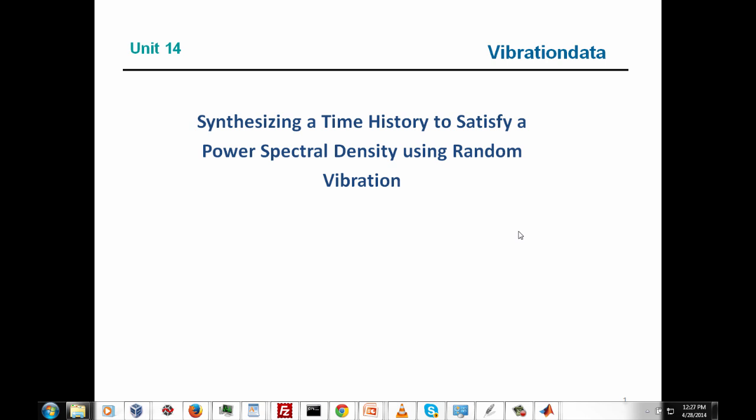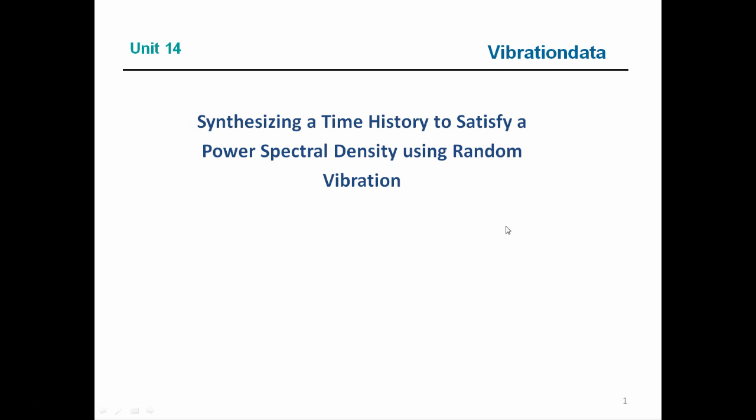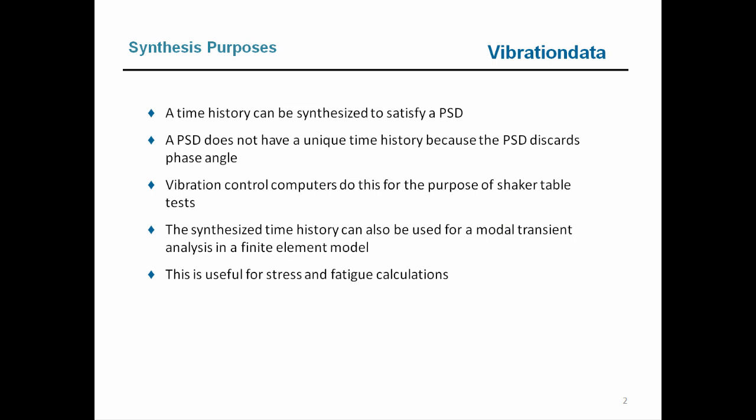The unit for today, we will be synthesizing a time history to satisfy a power spectral density specification using random vibration. And this will be broadband random vibration with a normal distribution. Now, a PSD does not have a unique time history because the PSD discards the phase angle.